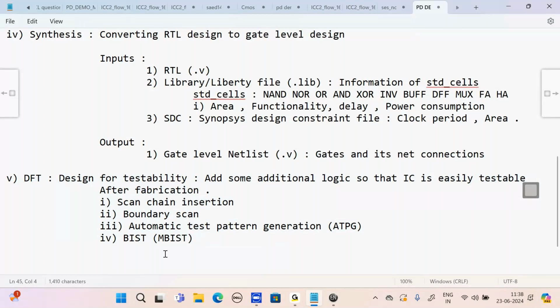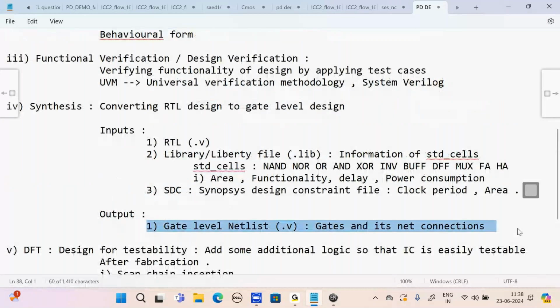Because see, what happens is, a physical design engineer will not do physical design only once. They will do it 4 times for the same project. Because they will first do a trial design. Next they will do a little bit proper design. Next they will do a little bit proper design. At last they will do what? Final design. Because when they are doing the trial design, your netlist is not completely frozen. Means the netlist may be changing, because the RTL team will still change some logic.